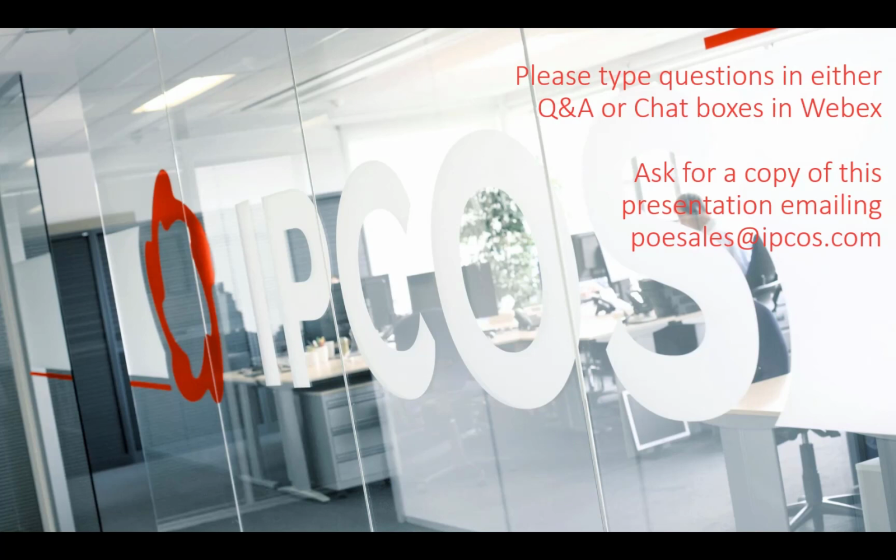But again, if you have an analyzer that is fast enough and reliable enough, I would say yes, you can do that. I mean, you have examples. It's not exactly distillation, but in furnaces, you can control excess oxygen. Why can you control excess oxygen in furnaces? Because it's such a simple and reliable technology that analyzers are very reliable and very fast. They really give you an instantaneous measurement all the time. If you can get something like that for your particular distillation column, then yes.